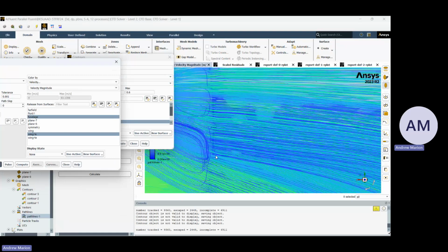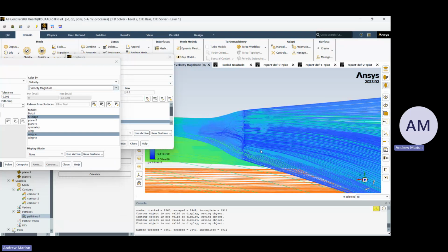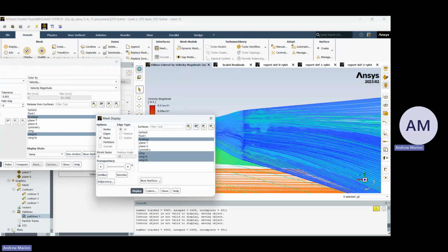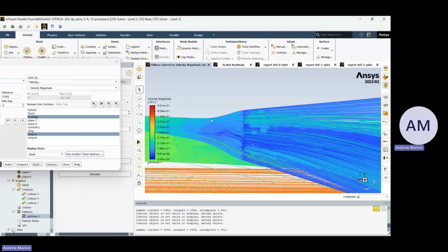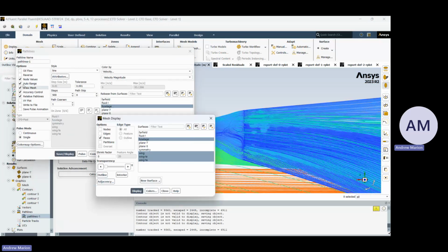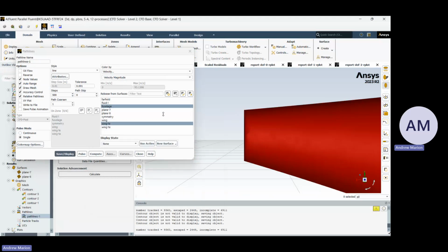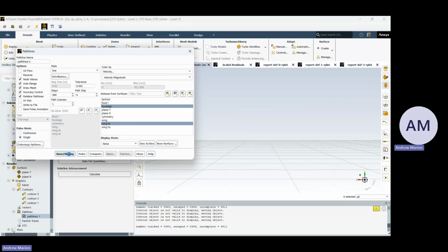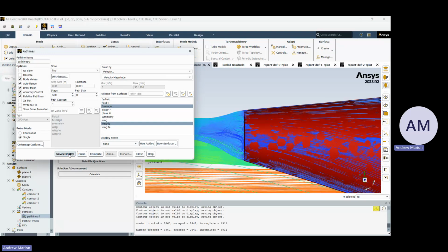And analyzing the shape of your fuselage is very important because your wing is not the only thing that generates lift. It's the most important thing for generating lift, but the shape of the fuselage can aid in lift generation or really aid in drag. And this is where all the different things for drag come in. A sharp cutoff like that will do drag really terribly.